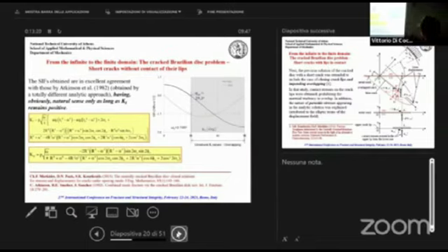It's very familiar to all of us. He predicted that assuming point loads, the limit is 30 degrees. Using a contact arc of 2 degrees, we found something like 29.3, which is very close. Up to this limit, the solution is acceptable from the natural point of view.